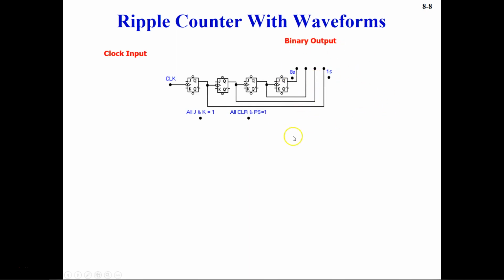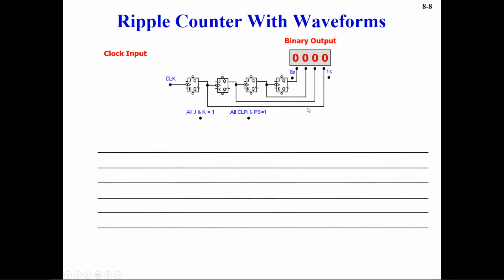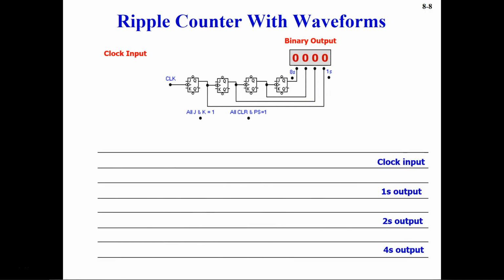So this is the same circuit which we have seen previously. Now the addition is to see the timing waveform. So let's see what will happen when the first pulse is provided. This is your clock pulse you see here. And you know that previously it was all 0 0 0 0. And when the first pulse is provided, these two JK inputs are in the toggle condition, which means J and K are equal to 1, so whatever Q was previously is going to toggle. So it has become 1, and that's what you can see here.